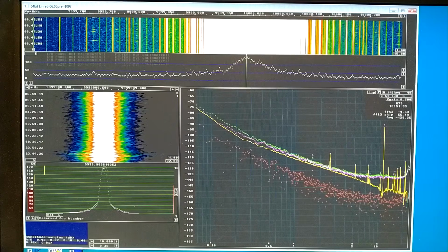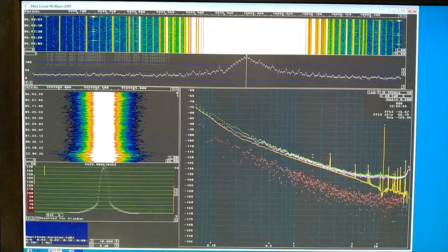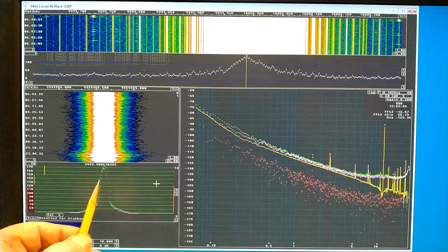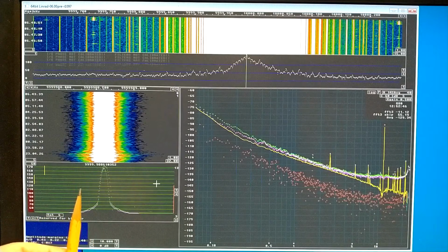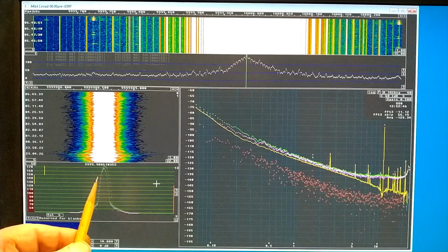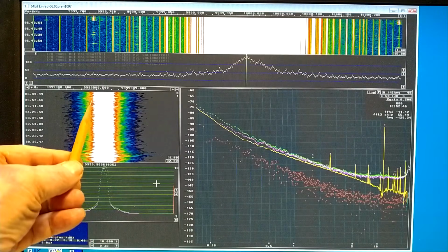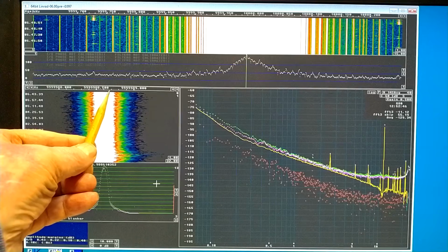Here is the phase noise as seen in Linrad. The amplitude and phase modulation is extracted with a coherent detector. In the baseband here there is a narrow filter. It is 0.05 Hz wide approximately, 0.1 Hz per division up here.